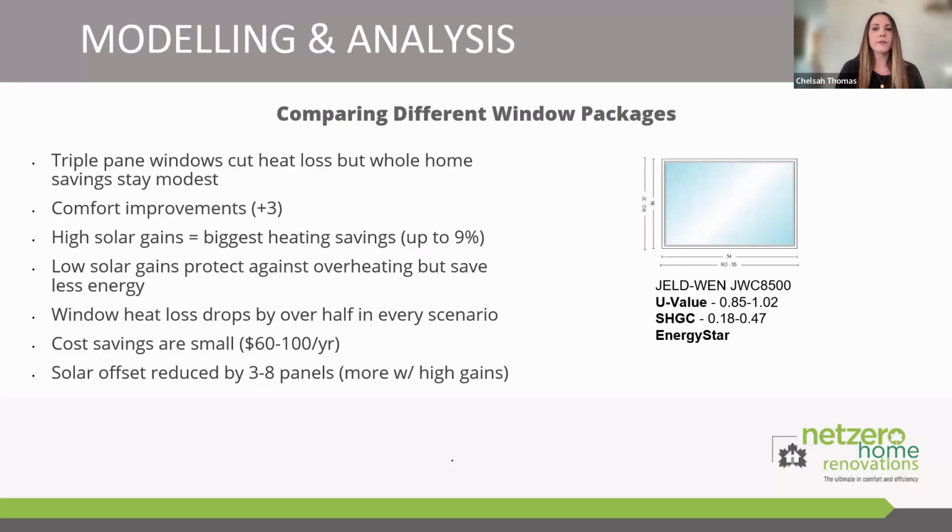Luckily, Robert had observed during the summer that the overhangs on the southwest or south side provided enough shading to prevent sunshine from directly impacting the comfort of those south-facing rooms, and were positioned to benefit the home for wintertime solar gains. Another factor considered was, as Robert mentioned, increasing the window sizes by about 20% on the south.